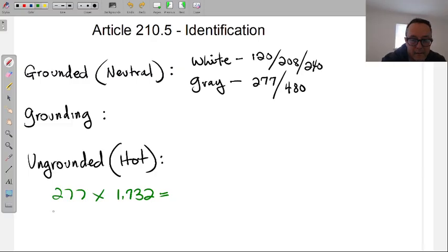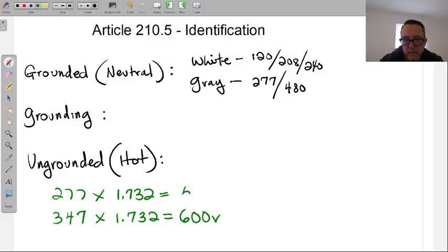By the way, there's another one out there, especially since you're out in California. They do have this voltage that runs around out there in industrial parks. Large manufacturing facilities will have 600 volts. These are the 3 Y transformers that are out there: 208, 120, 208, 277, 480, much more common in industrial, but also 600 volts.